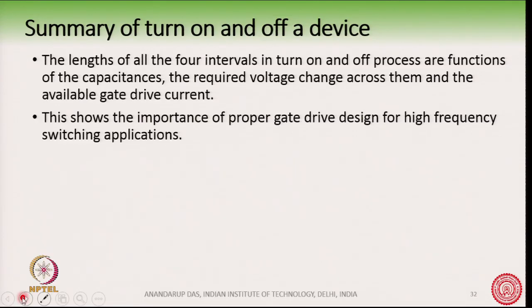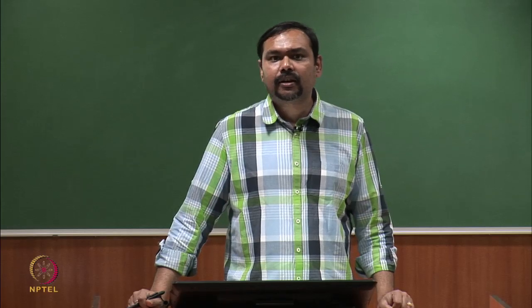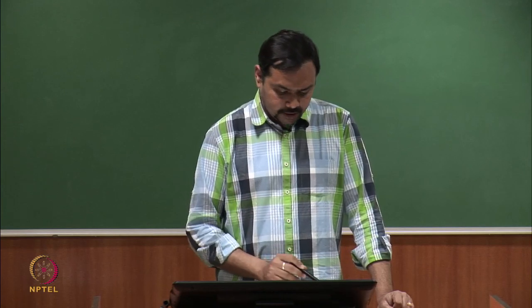So, this is what I wanted to summarize, that the length of all these 4 intervals in turn on and turn off process are a function of the capacitors, the required voltage change across them and the available gate drive current. So, for a gate drive design for high switching frequency application, it is important to properly choose these components.